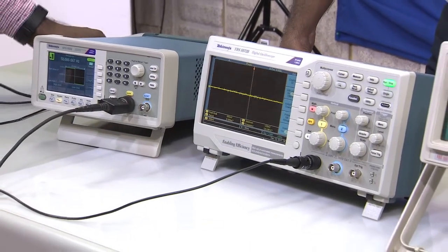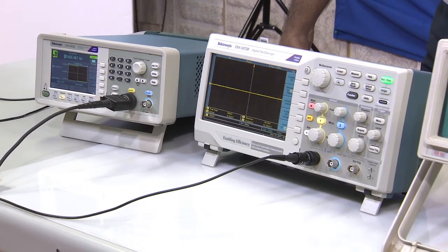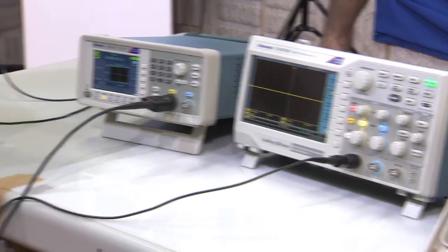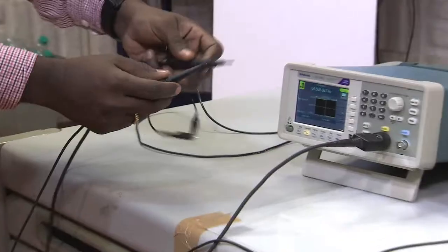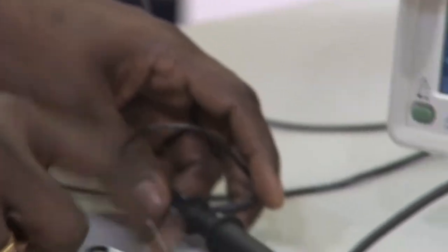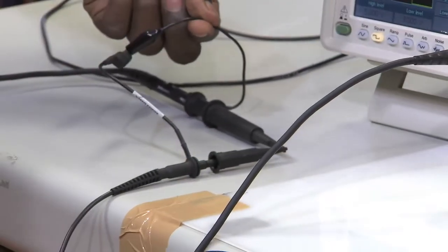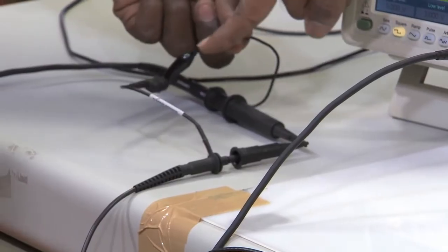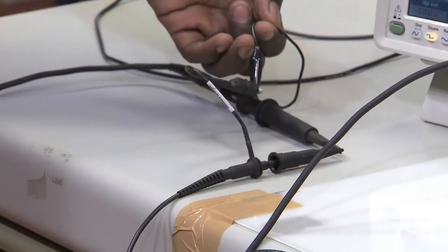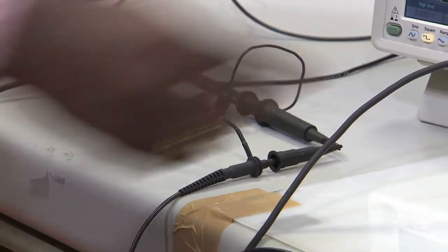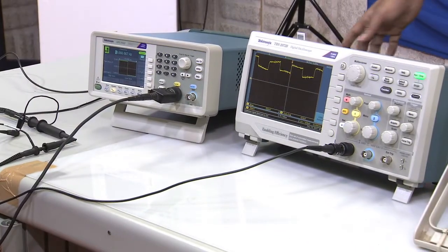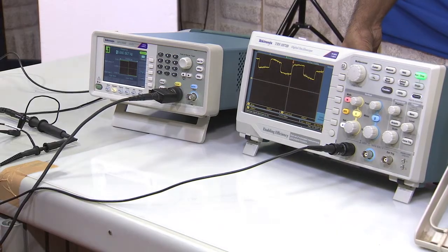Right now let us see what kind of waveform we can see in the oscilloscope when we connect. Can you please zoom in on his hand, so we can see. So, you see the probe has two long things, right, and he is connecting these two probes, and the shorter one he has connected to the shorter one, right. So, the shorter goes with the shorter one, the longer goes with the longer one. When you make the connection, now let us see how it looks on your system here, please. Yeah. So, you can see the square wave, right.